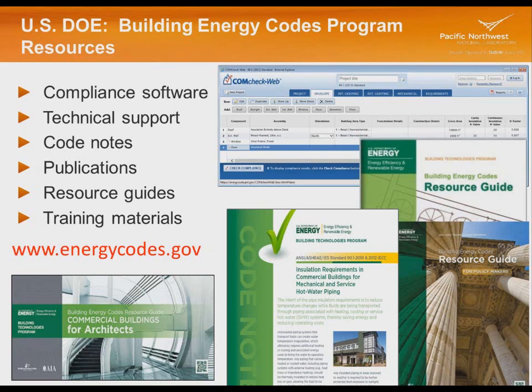If you went back out to the Energy Codes website, which is up on the screen, there is compliance software that Reed mentioned, the COMcheck software. It's a great tool. It'll provide a way to enter your complex or simple systems, run some of your takeoffs for your fans, for economizer requirements, and so forth. It'll actually customize requirements in a requirements checklist form. So it's great for a plan reviewer. It's a really good resource for designers to use to create a really good report that can be used to plan review and to inspect to.